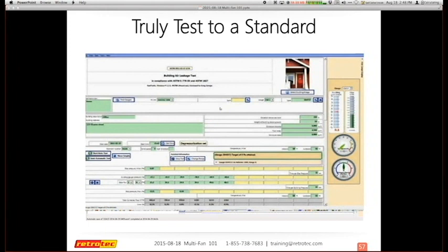So if you're going to go from 20 pascals to 75 pascals, I need to make sure that I've confirmed that I can actually reach those test pressures with the fans I'm using in the same scenario. So I know they're not battling at a certain point, or I don't have to pause and change ranges. Or if I do, I need to know that so I can plan accordingly. So that's definitely one key part of that.